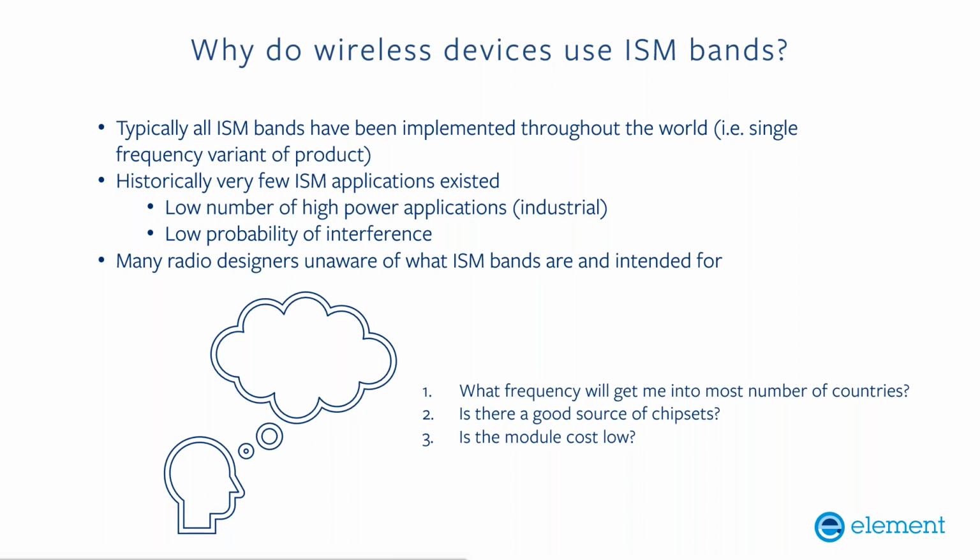So I can imagine that if you were a designer, in your head, there would be certain thought processes that you'd be going through. And to me, when I was thinking about this, I could imagine that I would go, well, what frequencies get me into the most number of countries? What frequency band product will get me into the most number of countries? Is there a good source of chipsets or modules? And what's the unit cost like of that? And if I can answer all three of those positively, I would probably end up designing my device around those sorts of chipsets or modules that I could buy in and use within my device itself.